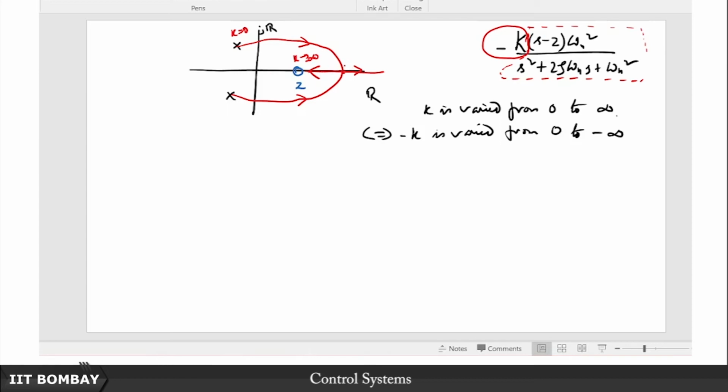But we don't even need to evaluate all of that. We can just do a qualitative analysis and see what happens. Even through a qualitative analysis, we may infer that a right half plane 0 such as this, or a non-minimum phase 0, clearly has a detrimental effect on the system. Just like a pole on the left half plane pushed the root locus to the right, and it went along the asymptotes. But here it does not even go along any asymptotes. It only goes along this 0 degree line, that is the one asymptote, but the other branch terminates here.